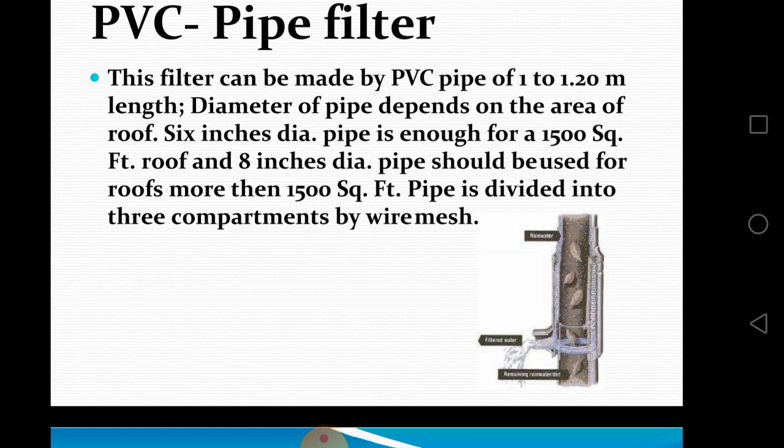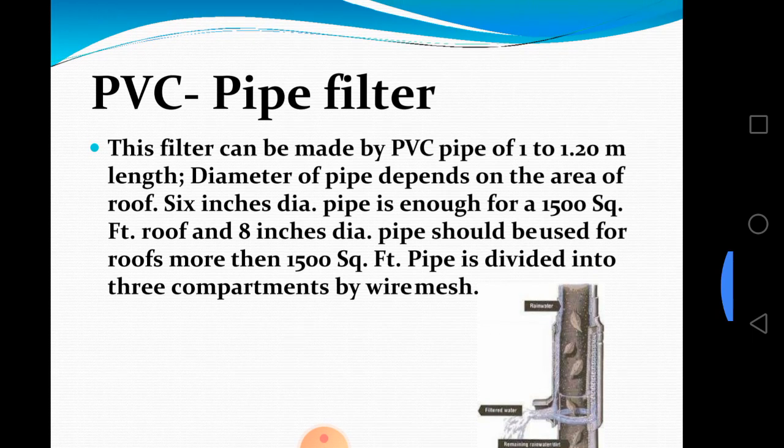So water yield from a catchment depends on the amount of rainfall, watershed shape, slope, types of soil and vegetation, and the evapotranspiration ratio. Accordingly, rainwater harvesting potential varies. It depends on the area, how much the rainfall is, its intensity, its duration, the slope of the land, and the kind of soil. Infiltration depends on soil type and the vegetation of the area.